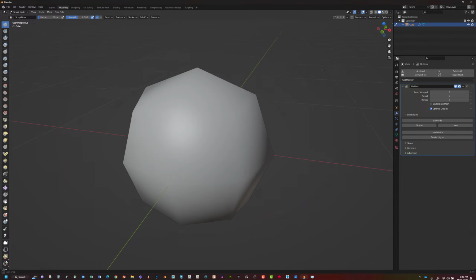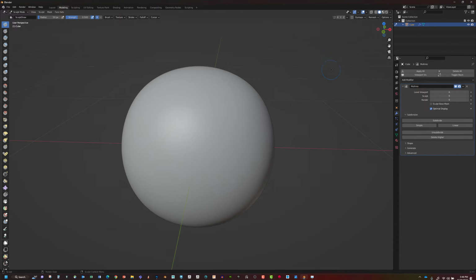I had to do a little bit of digging, and I was able to find in this options menu right here, under display, there's fast navigate. So if you want to turn that off and you don't want to have that going on, I do believe that this is for purposes where you've got a lot of dense meshes and it's slowing your machine down. You can turn that on, so while you're rotating it drops down to a lower resolution. So if you're just working with one object like what we've got at this time, this is probably just fine for you to turn this off.